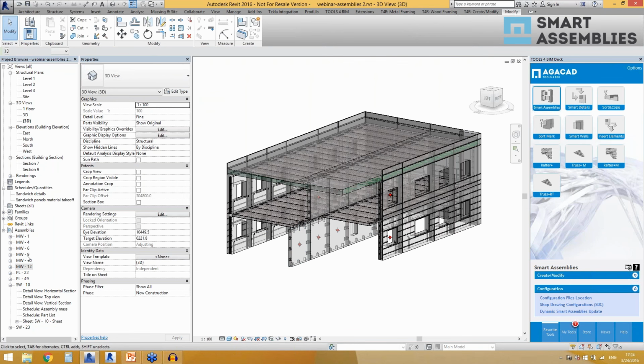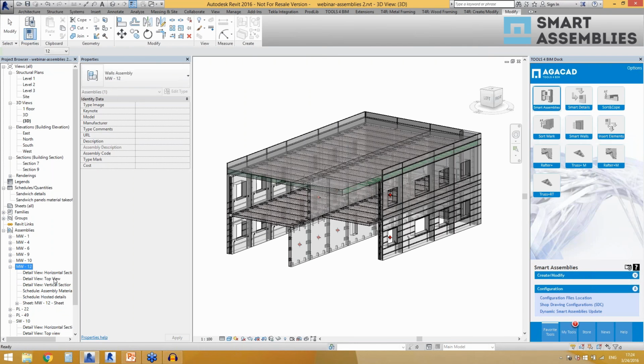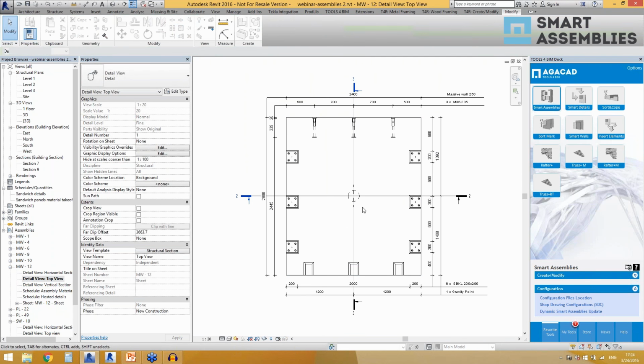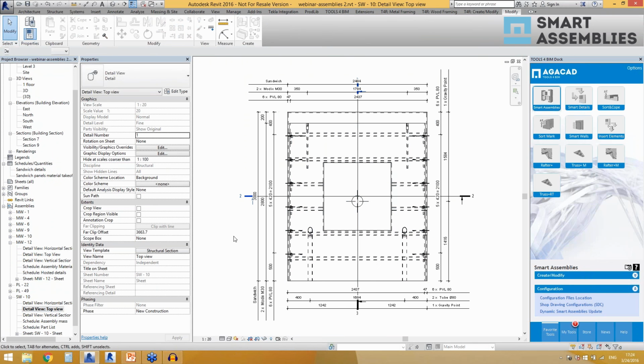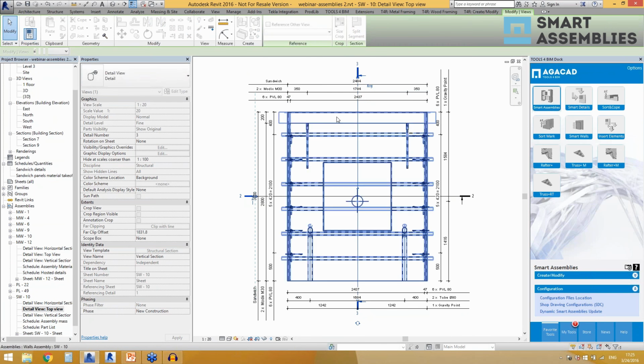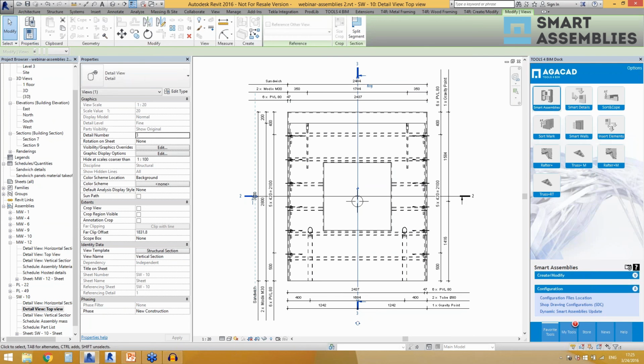Let's say, I'll take a look now. Yeah, it will move symbols outside the dimension. You see, in this configuration I have used this option, and in this configuration I didn't use it, so you see that the symbol is on the dimension line. So you will have to move it manually if you do not use this in the configurations.